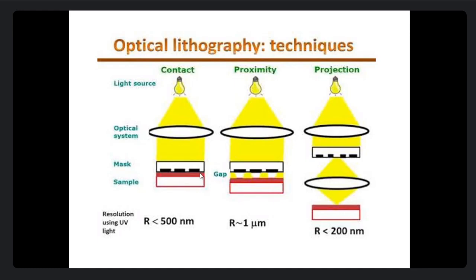as your gap increases, the possibility of contact between this mask and the sample or the wafer reduces. And as it reduces, automatically the contact related issues, mainly some kind of defects or errors, can be ruled out or mitigated, whatever you say.